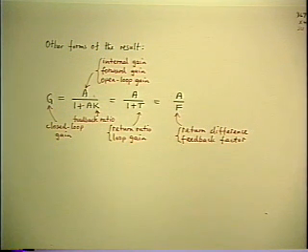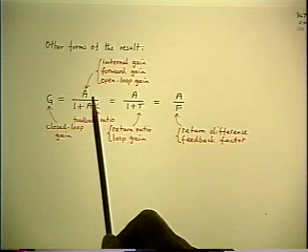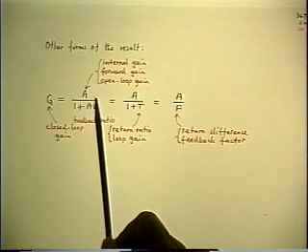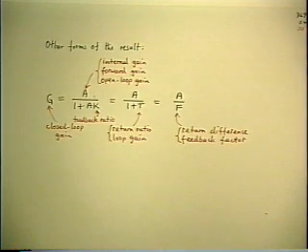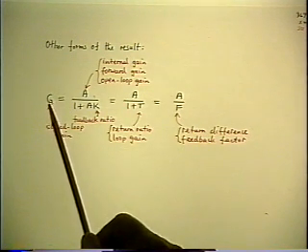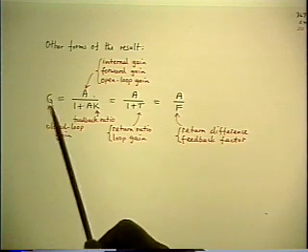So that's a basic problem with the conventional approach, and so I'm suggesting an alternative approach, which is potentially beneficial, because not only is the A, for example, difficult to calculate directly by breaking the loop, but it isn't part of the answer that you're interested in anyway. The G is the thing that has to meet the specifications. That's what the ultimate outcome has to be.